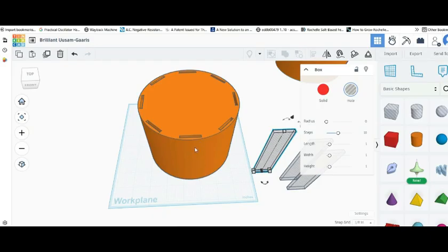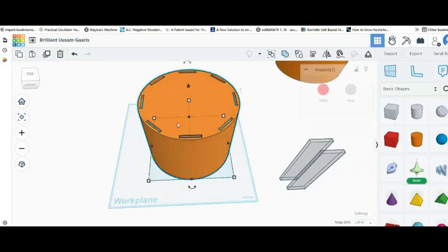So that's good, but do we have enough space between the magnets? And we don't want to overlap, so we're going to want the coil to be the same width as the magnet. And what I want to do now is just get an idea whether those things are going to step on each other's toes. So boom, boom.